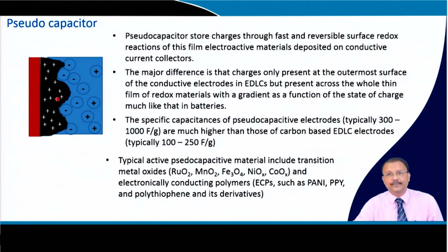So, certain pseudocapacitor which is not electronically conducting, you need to use a carbonaceous material to make a composite. There the idea is that a fast and reversible surface redox reaction takes place. It is not the adsorption of the counter ions on the charged surface, but there is a redox reaction involved. So, that is the major difference, that the charge is only present at the outermost surface of the conductive electrodes in EDLC, but it is present across the whole thin film region.